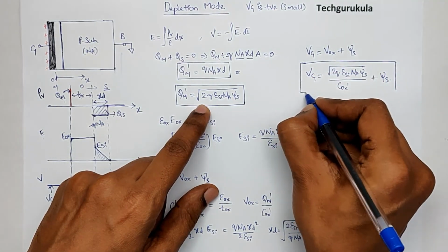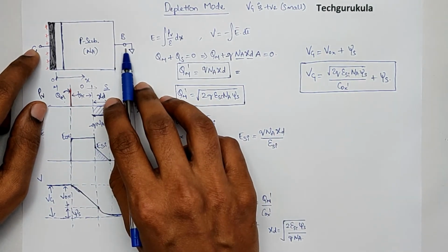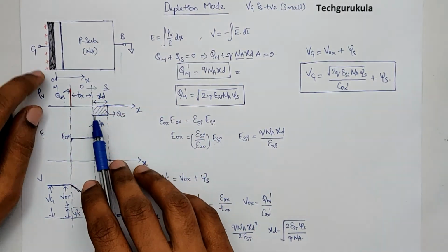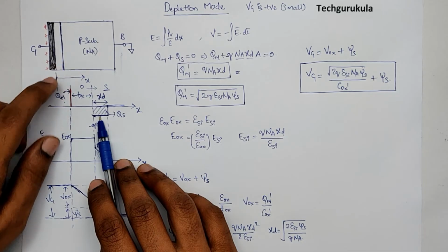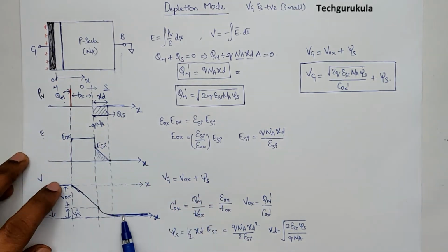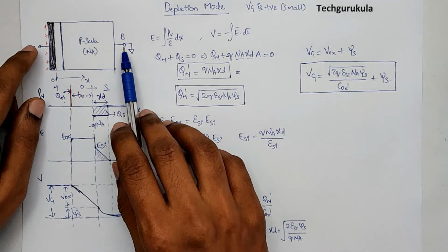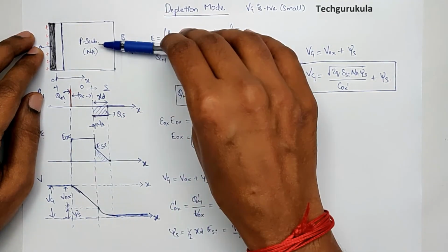This is the potential applied at the gate with respect to the bulk, and due to this there is charge built up on the gate and semiconductor, due to which there is an electric field, due to which there is a potential difference which should be equal to the potential that we have applied here. So everything should be satisfying.